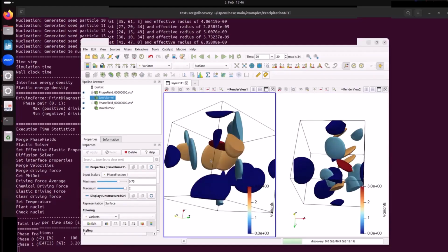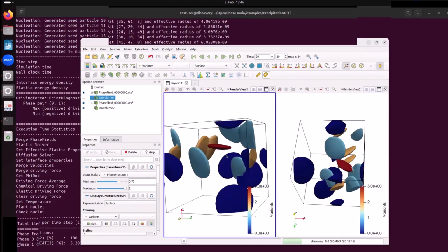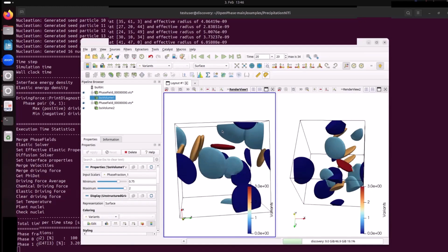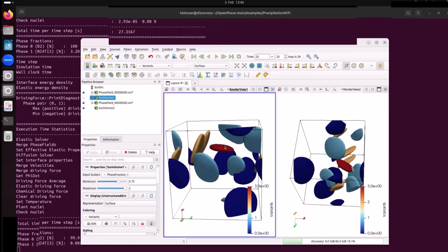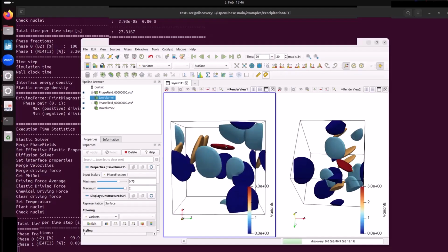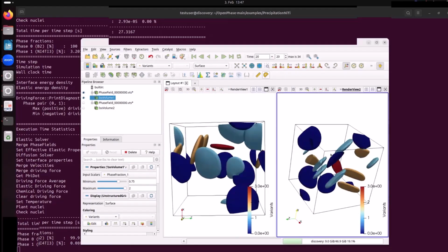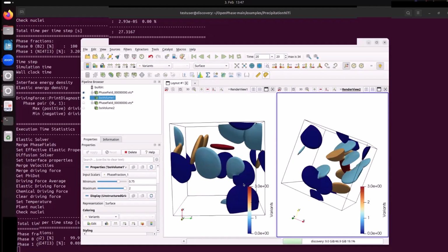While here, one variant, this one, is oriented nearly perpendicular to the 0, 0, 1 axis. That actually was our intention. So slight misalignment just because we didn't use 0.95 radians, but just one, which is a little bit of an overshoot. And this one variant compared to this structure, you see, is already rotated. So this is how you can change the orientation of your reference volume and simulate again, or how multi-grain simulations are performed. So different grains have different orientation, and it's automatically taken into account by rotating the entire structure inside.